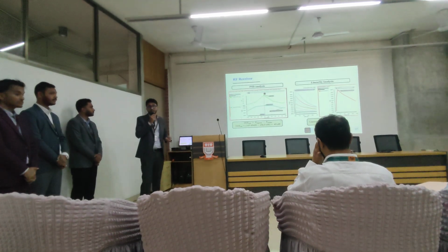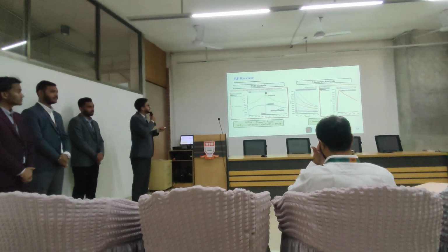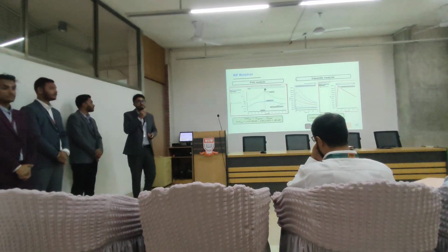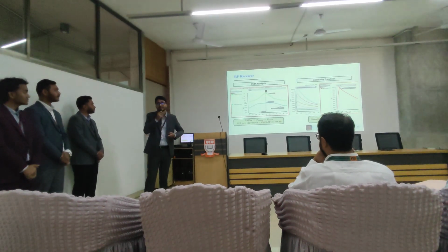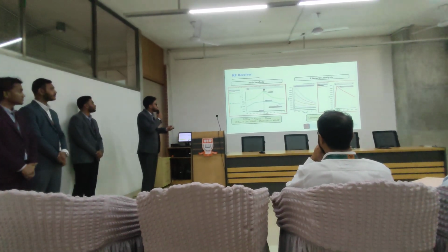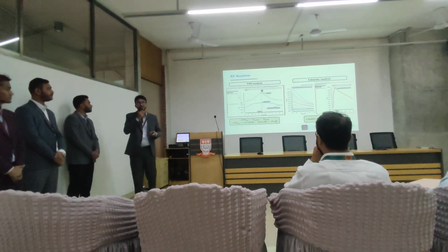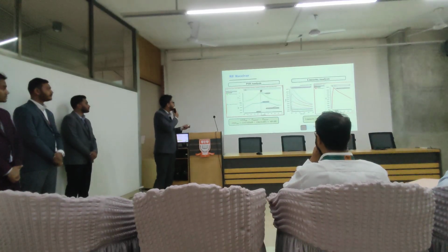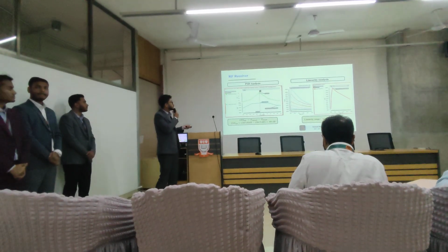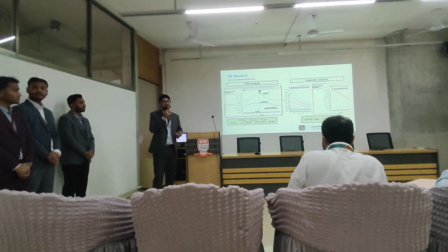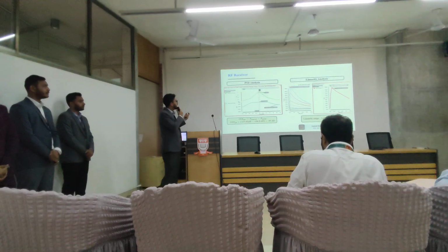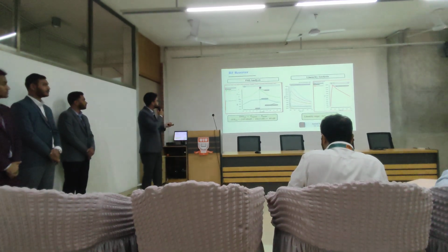So now let's talk about the signal quality and the linearity analysis of our RF receiver block. The DFT analysis shows that our signal is more distinct than the noise, and we get an SNR of 49 dB from the DFT analysis. That means our output is more reliable. In the linearity analysis, we find that our input range is 1 microvolt to 1.3 millivolts. This is a wide range of input voltage that ensures our RF receiver design is reliable.